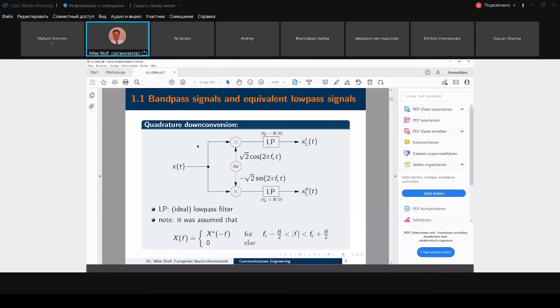Sorry, this is up conversion, this is the band. Sorry, that's wrong. We are in the bandpass range. Then we do down conversion, and then usually here we have an ADC, here we have an ADC. Then we do the processing truly with complex signals at a much lower frequency range, which is good for technical realization. Okay, that's all. See you next time.